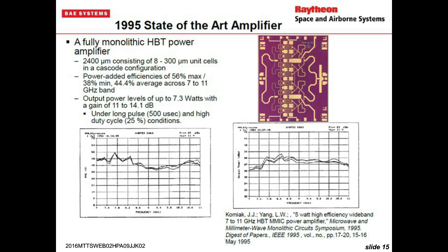unilateral, reduced S12 as a combination, and it makes an amplifier that usually has about 1.5 times the gain performance of a single-stage amplifier in the size of a one-stage amplifier. And this one was likewise a state-of-the-art result with about 45% average efficiency across a sub-octave 7 to 11 bandwidth with up to 7 watts of power output.